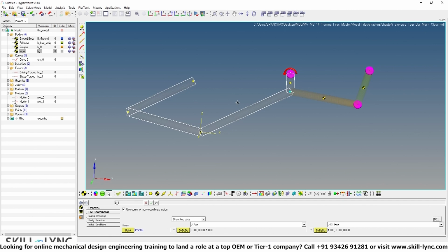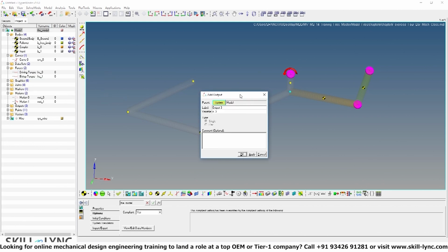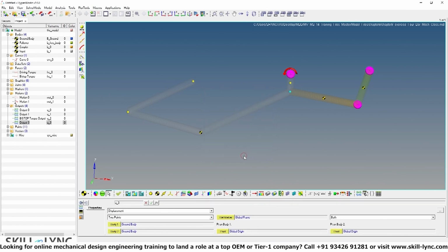For this, let's go to the project browser. So this is your project browser, and you right click on your model, say add, and go to general MDL entity, and then say output here. Okay, so you'll be creating outputs. Once you do this, you can leave it default, and just say okay.